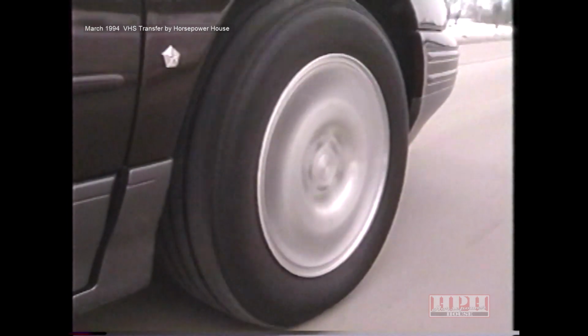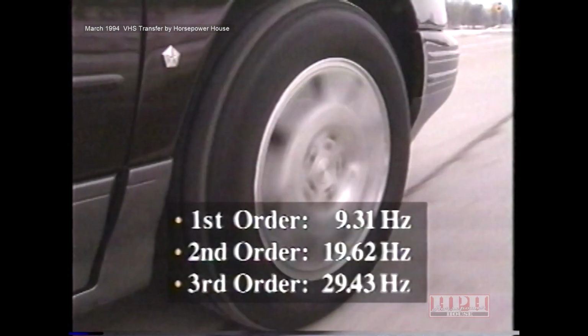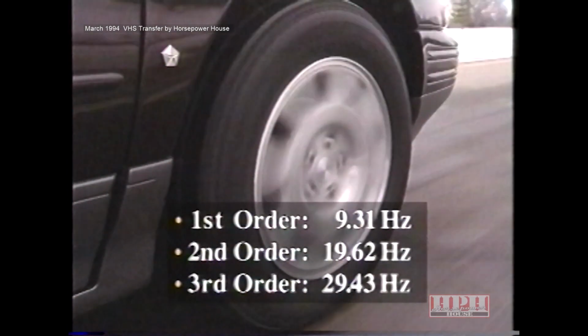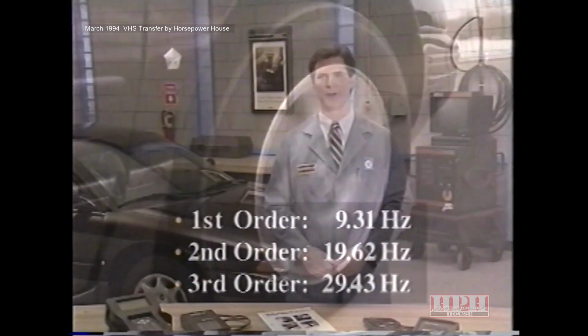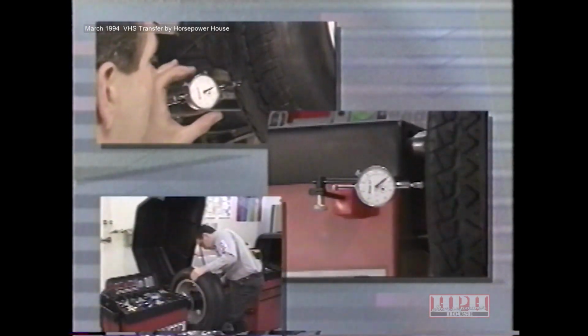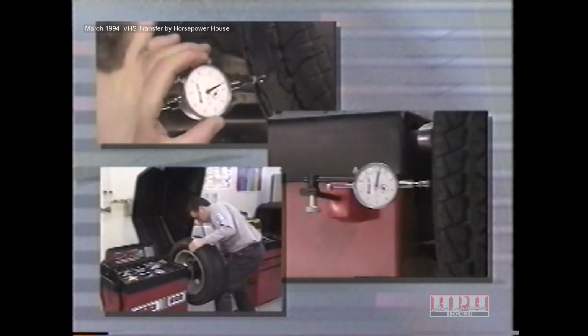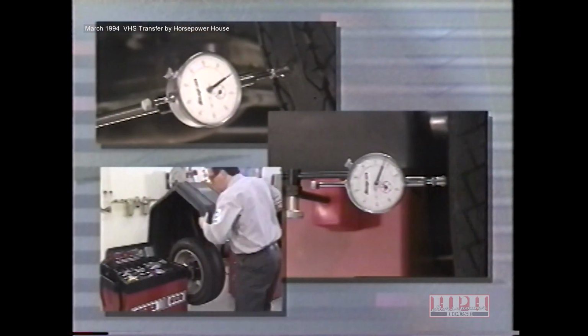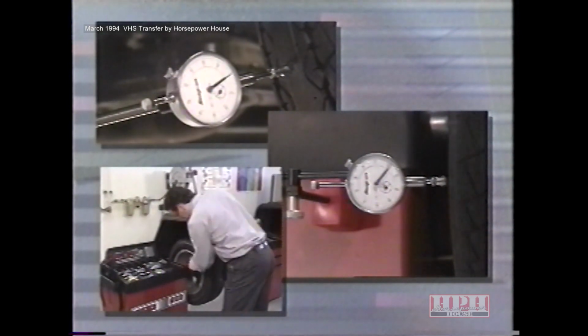If the symptom's vibration matches the first, second, or third-order vibration, it is most likely the result of problems in the tire wheel area. First-order tire wheel vibrations are usually the result of one of two conditions, excessive runout or excessive imbalance. These conditions must be eliminated step by step in order to attain a set of wheels and tires free from vibration-causing elements. Refer to your service manual for proper procedures.